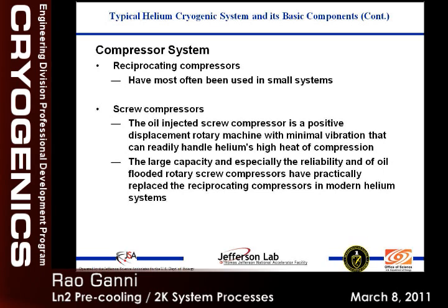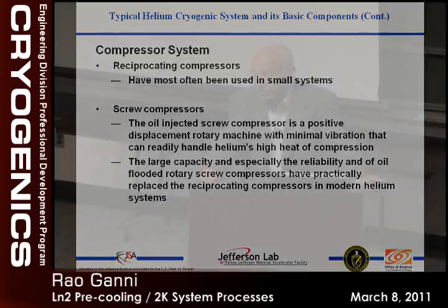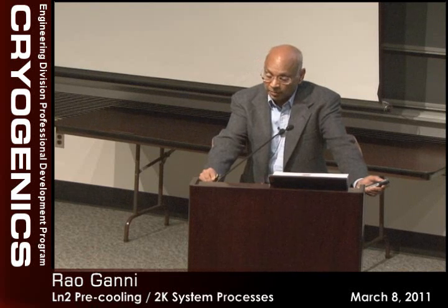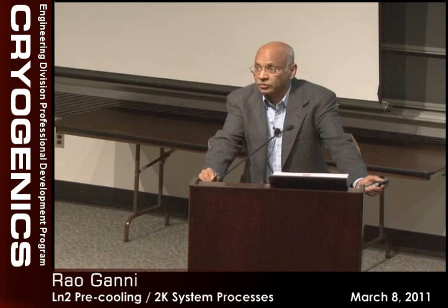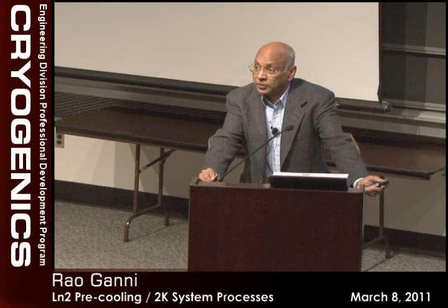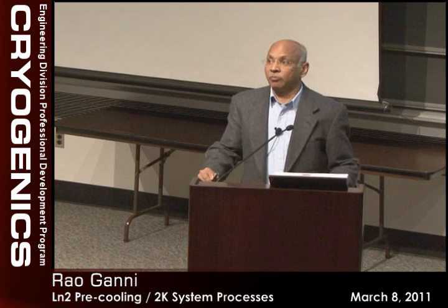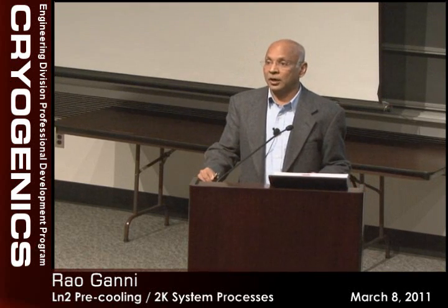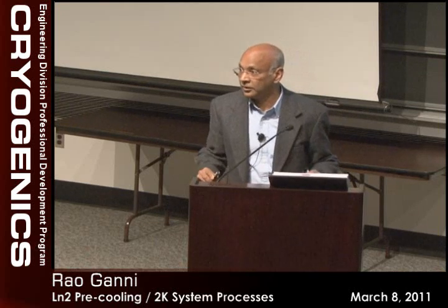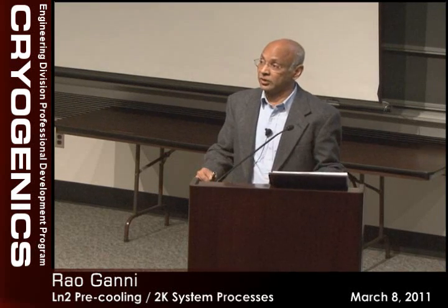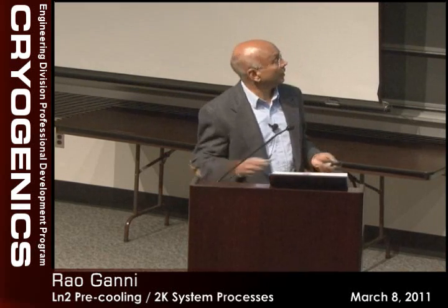And in the screw compressors, that's become basically the standard in the helium refrigeration industry because of less vibration and less maintenance. Although the screw compressor guys will tell you every 30,000 hours you have to tear it down, a lot of our compressors are running around 75,000, 80,000 hours. We figured out by letting them float to manage it, more than doubling the life in between tear downs. Most of the compressors at CHL, ESR, and CDF have 70,000, 80,000 hours.